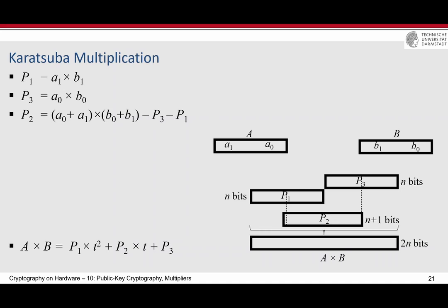After that, you need just an adder, and the adder should not take the 0 here because the output of this part is exactly P3. But definitely you need an adder to take the n/2 bits of P2 and add them with P1 completely, from here to here. And then if you don't have this multiplier, you need to divide again, and again, and again. So you can implement this in a recursive way.